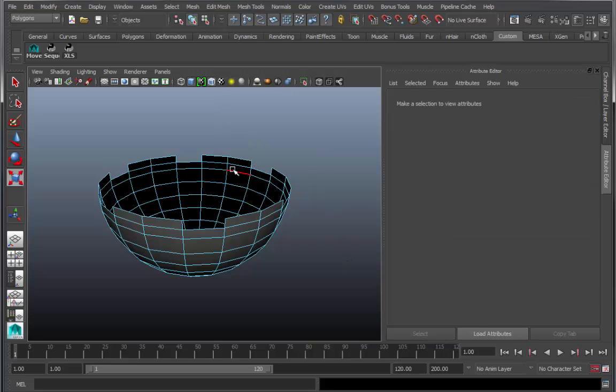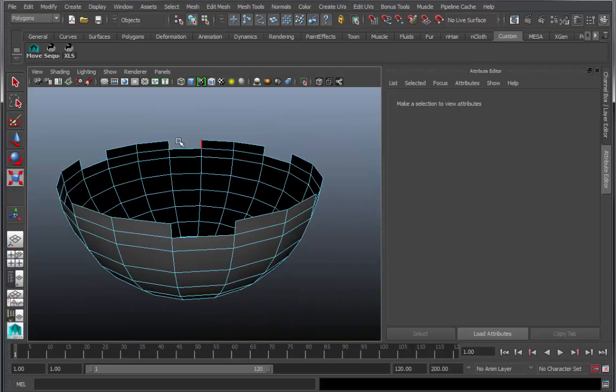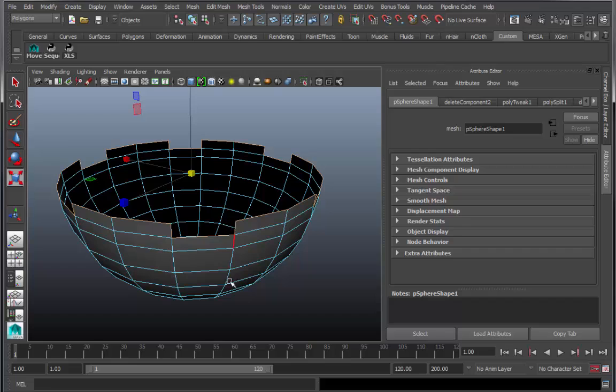Now Maya's pretty smart. Maya's pretty intuitive with little shortcuts. And one of its shortcuts is when you are in edge selection mode and you quickly come in on an edge that's part of a circular lip, even one that's been broken like this one, where there are new divots because you've deleted the original face there, were you to double click on an edge, it will select the whole of that ring. Observe. So there. It's worked fine for me just now.